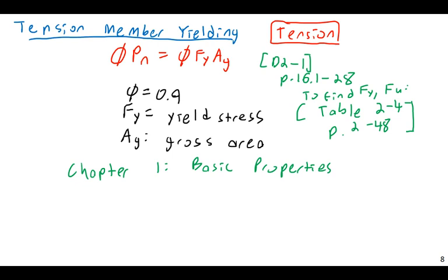They're listed in a great big table in Chapter 1, and you can just go through there and say, if I want to know the cross-sectional area or the moment of inertia about either axis for a certain W shape, I just look it up. I don't have to calculate it every time. That would get very tedious.